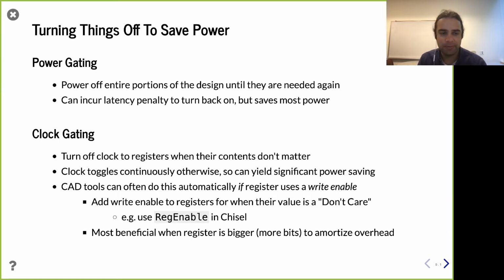So really, as a conversation about clock gating, the conversation isn't whether the tools can do this. The question is, what did I do wrong in my Verilog to prevent the tools from doing this? Depending on semantics and the way your design is written, like with design tools reading Verilog, or C being read by a compiler, the tools normally aren't allowed to change the semantics of your design. So you'd be very conscious of the semantics you're requesting.